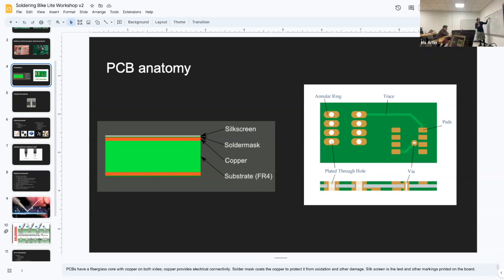The insulating layer in the middle that used to be brown and is now more commonly clear to gray is just a different insulating material that we started building circuit boards with in, I would say, the 70s to 80s. The more modern material is not as friendly for working with at home because of its fiberglass. If you want to cut down your circuit board into smaller pieces because the project is smaller, you probably shouldn't be cutting fiberglass at home because you'd be inhaling fiberglass dust.